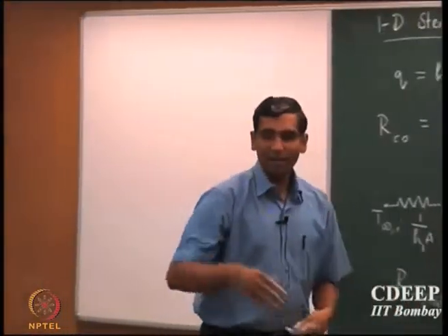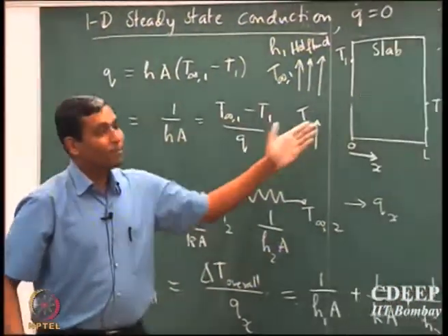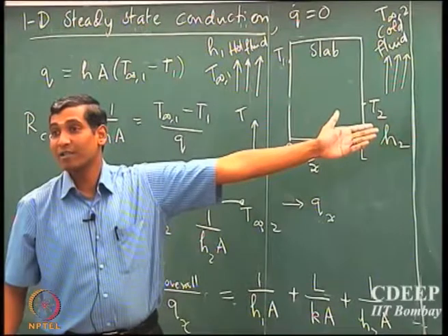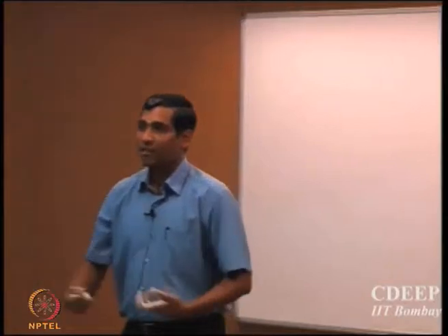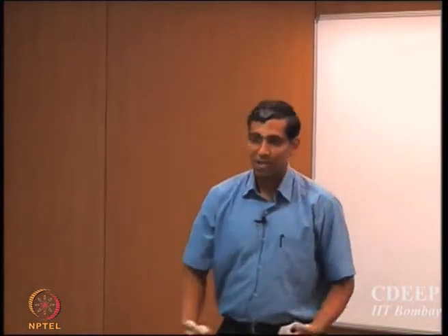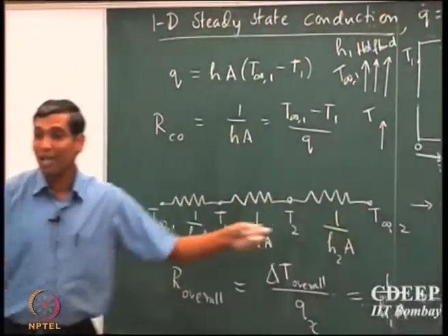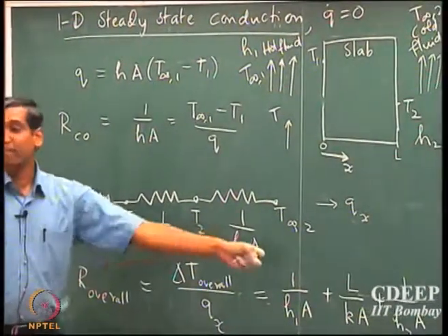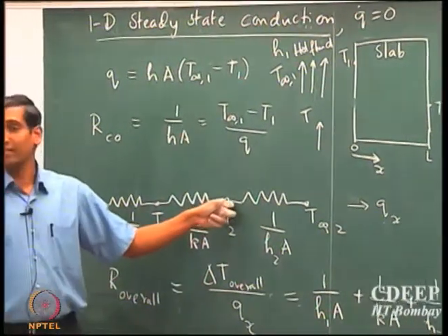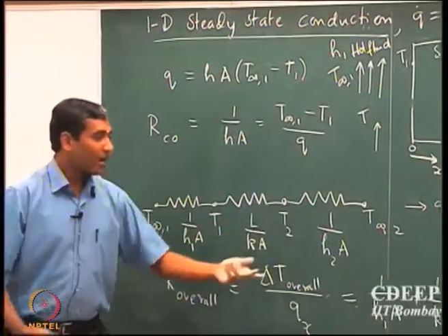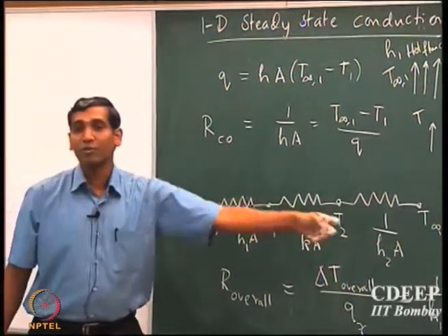If you take the example of the geyser, all that you can measure is the temperature of the fluid that comes in and goes out. So can we write our model equations and mathematical expressions in such a way that we are able to use the observable quantities to estimate the properties of the system? For example, I want to know the temperature T2, but I can only measure the temperatures of the outside fluid.